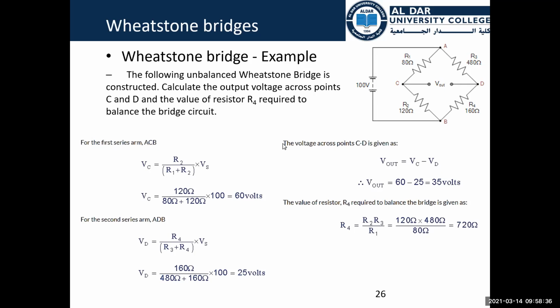So we are balancing the Wheatstone bridge first. We have the difference between C and D equals zero. Now, if any of the resistances is affected by a physical phenomenon or physical measurement, it will be reflected directly on the avometer, or the value here will be different than zero, higher or lower than zero.